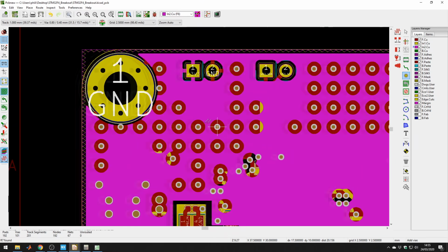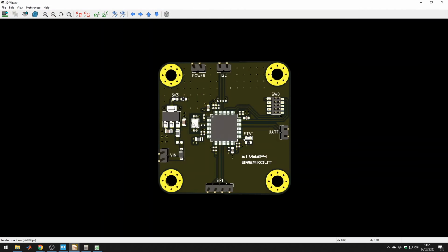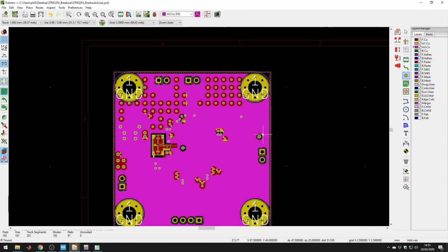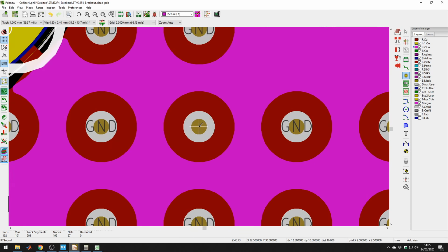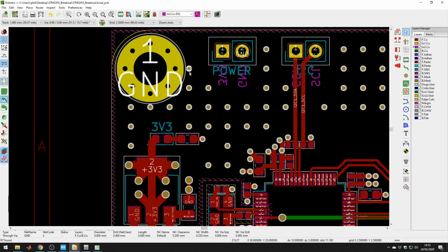It's really chopped up, and that's not very good. So, while it might look cool, you kind of want to go with a larger spacing, because this is completely chopped up, so only current will flow through these little paths here. It's fine for the ground layer, but not anything else.